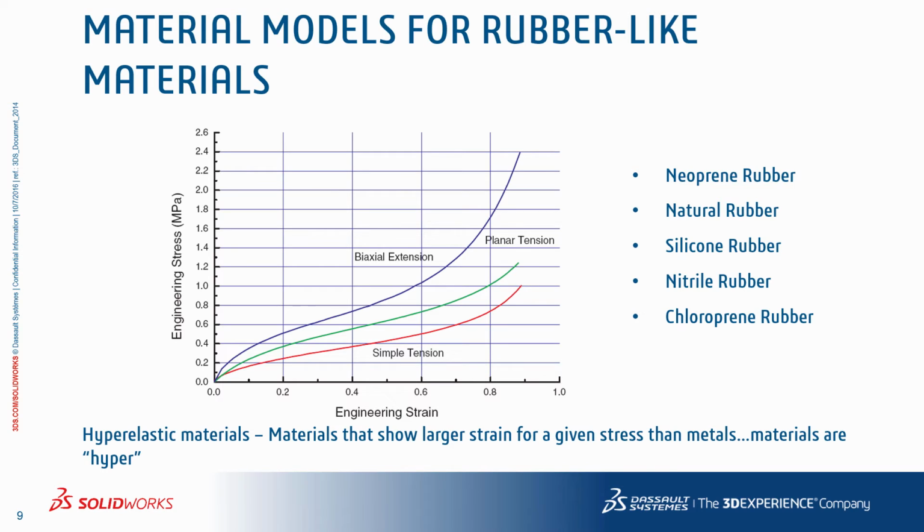Now, another class of common nonlinear materials that warrants discussion is hyperelastic materials like rubber, foam, etc. They are characterized by the capacity to take large amounts of strain with relatively small loads. Even though we treat the materials as elastic, isotropic, and incompressible, their behavior is very complex and depends on the loading mode. The amount of strain accumulation can be anywhere from 100% to a whopping 800% strain, which is literally 8 times its original size.